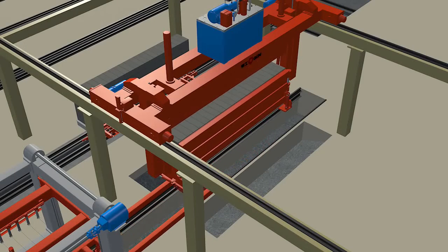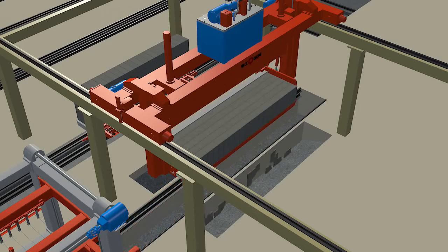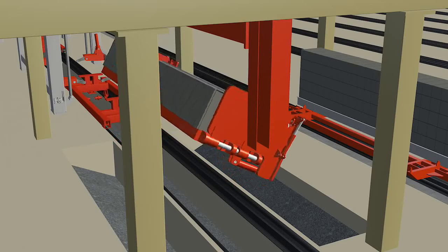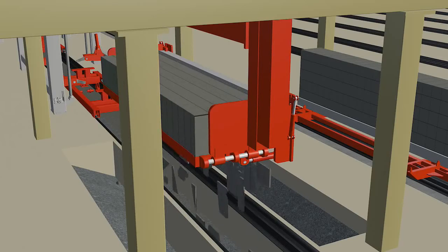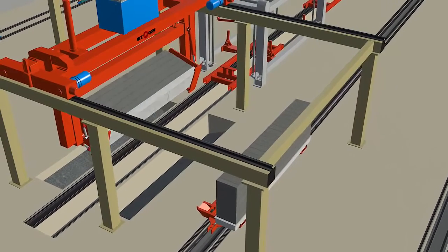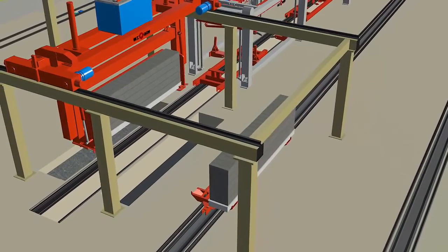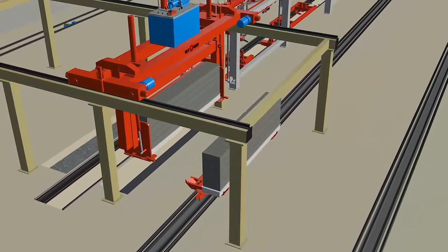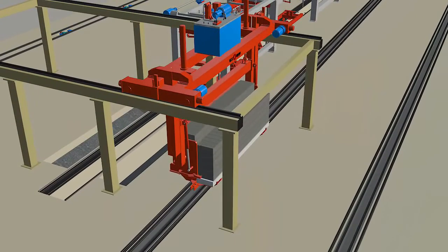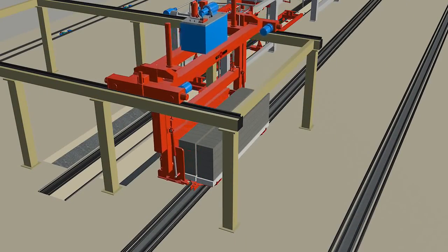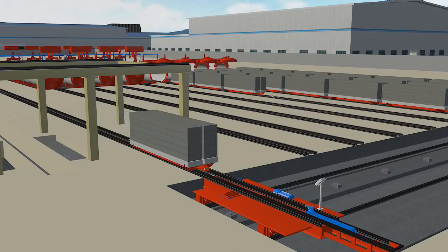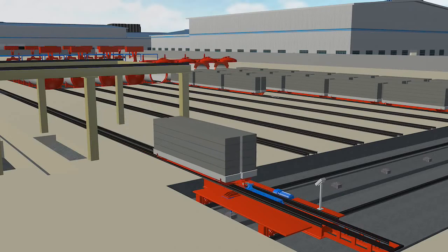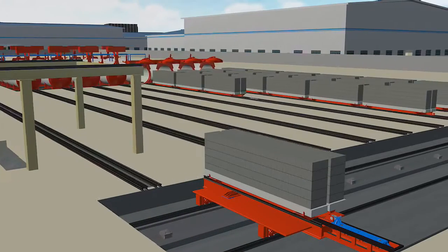The top and bottom layers of the waste fall down when the crane uplifts and turns the cake. The crane transports the cake to the autoclave ferry car, and the ferry car goes into the autoclave by the automatic tractor.